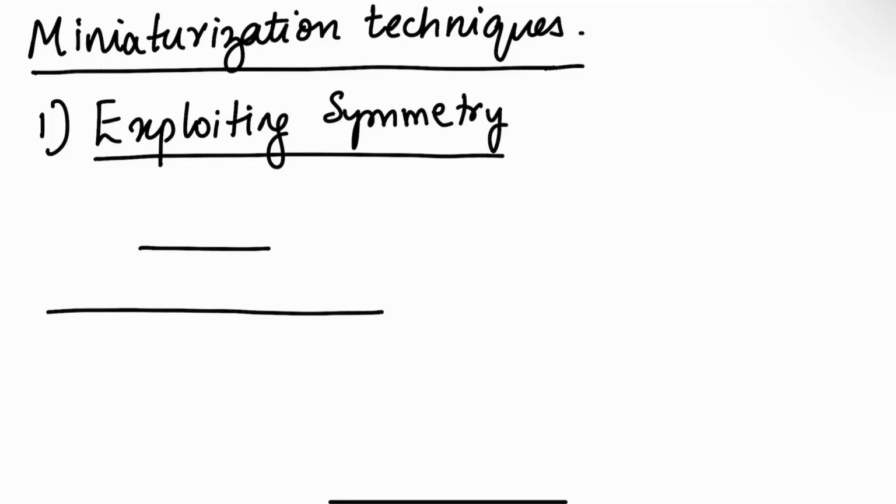And we said, okay, impedance is 0 here on this line, and it's somewhat symmetric with respect to that line, right? Because the impedance is 0 here, I can simply short my patch here. Short circuit is a 0 impedance, so I'm forcing a short circuit there. When I force the short circuit there, I can remove one of the sides. Of course, you have to remove the side which doesn't have the feed, right?